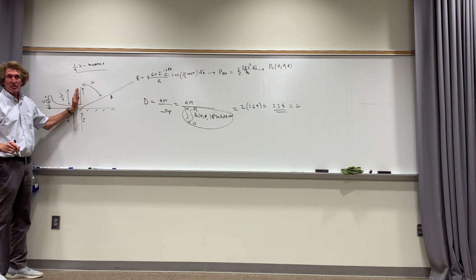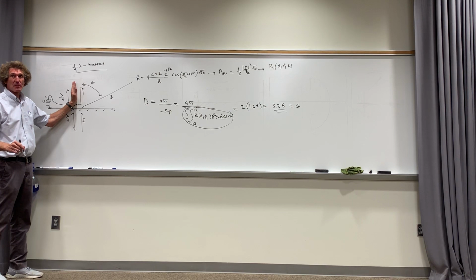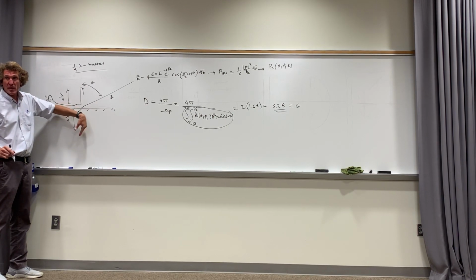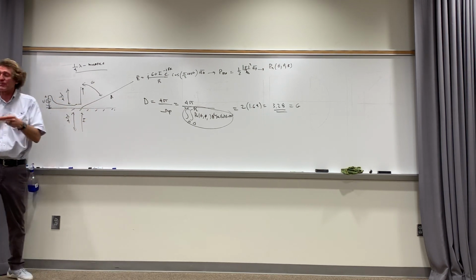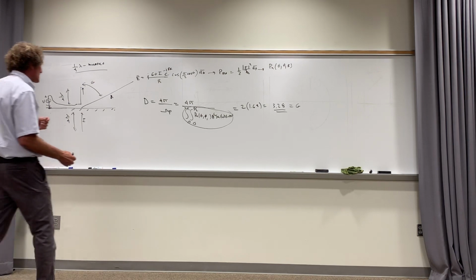Y'all agree that the amount of power radiated in the upper plane would be the same as for the upper plane of a half-wave dipole, do you agree? And wouldn't that be the same power that would be radiated in the lower plane if there was a true half-wave dipole? So in a nutshell, I'm saying since it's only radiating up here, it's radiating half of the power that it would if it was a full half-wave dipole. Does that make sense? What that means is this.